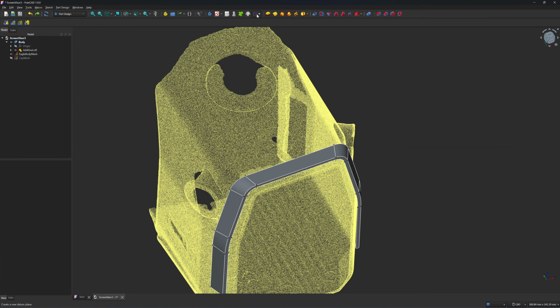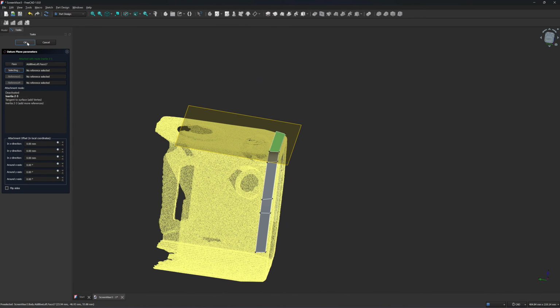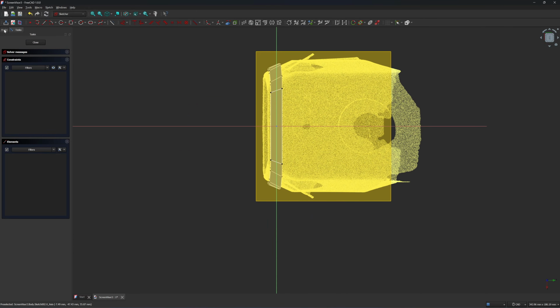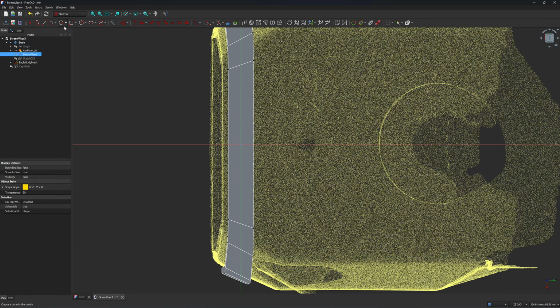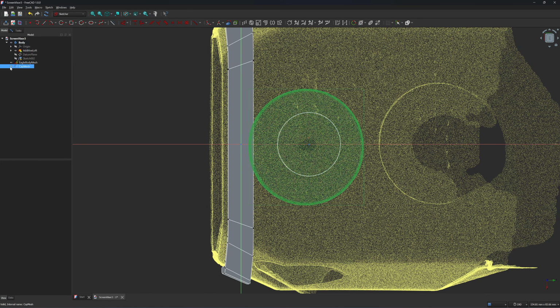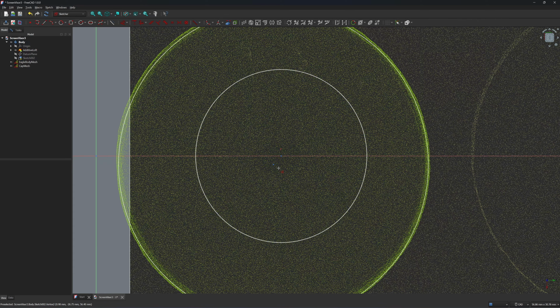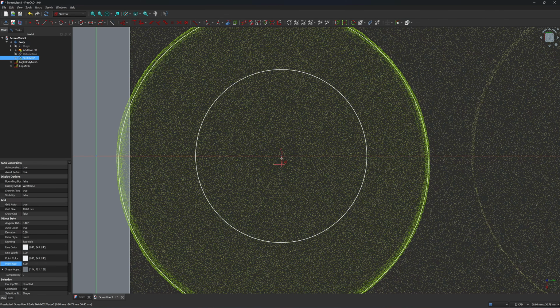I need to create a datum plane. Click on OK. Click on the plane. Create a sketch. Let me turn off the plane. Okay, and you can see that there's a faded line, and I'm going to turn on the cap. So the cap is not in the center. I'm going to create a 3-point circle. 1, 2, and 3. I'm going to click on here and here.